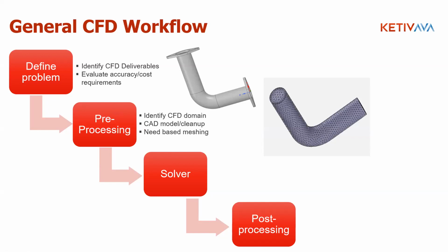Now, sometimes you may not want to invest so much time in actually going into the geometry and cleaning it up. That's okay. There are options available to you wherein you can wrap a mesh around your geometry in order to fix those holes and fix those errors. But in a standard case, by default, I'm assuming that if you're looking for a very accurate solution, you would want to go in and clean up the geometry.